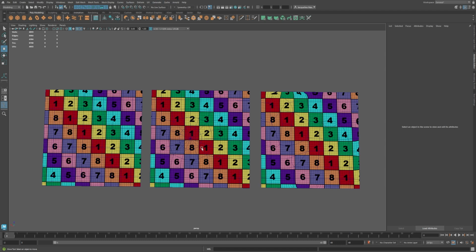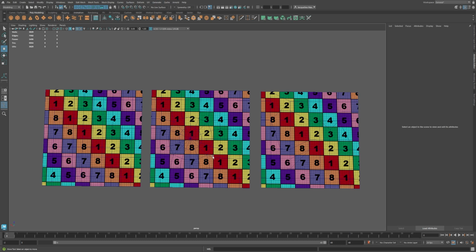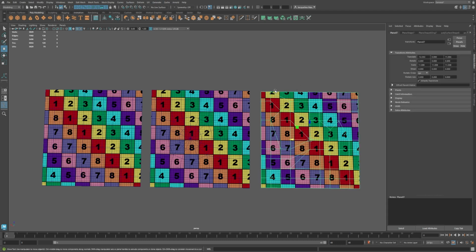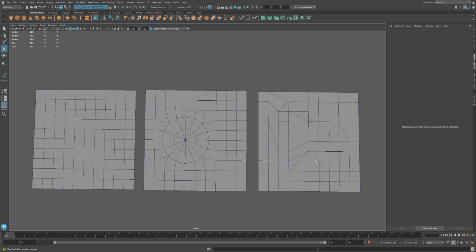And what we can see is that inside there's no deformation. The problems that we're seeing are here outside on the perimeter because we have an uneven distribution of edges, so we're getting a pull around the outside. But the triangles that exist within are not actually what's causing the problem. It's just the uneven edges. So when a shorter edge is by a longer edge, it's going to pull towards the longer edge when it's smoothed.